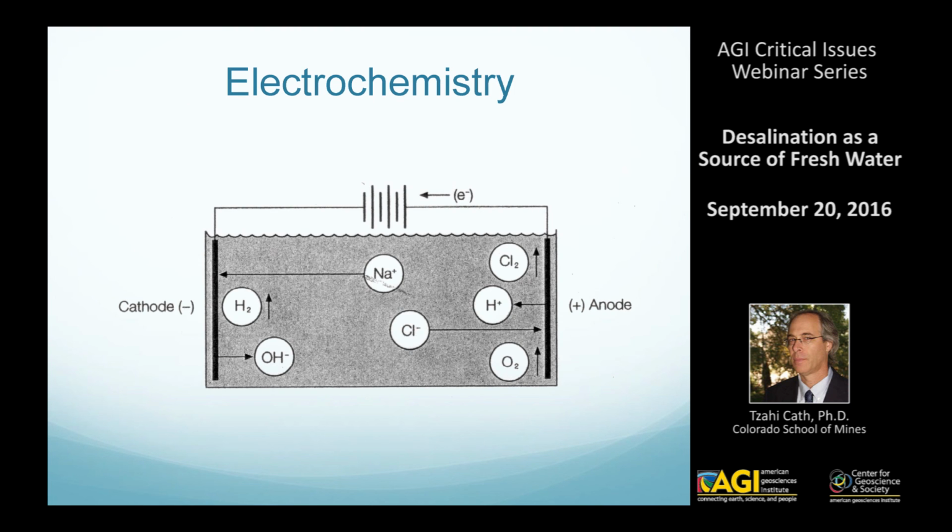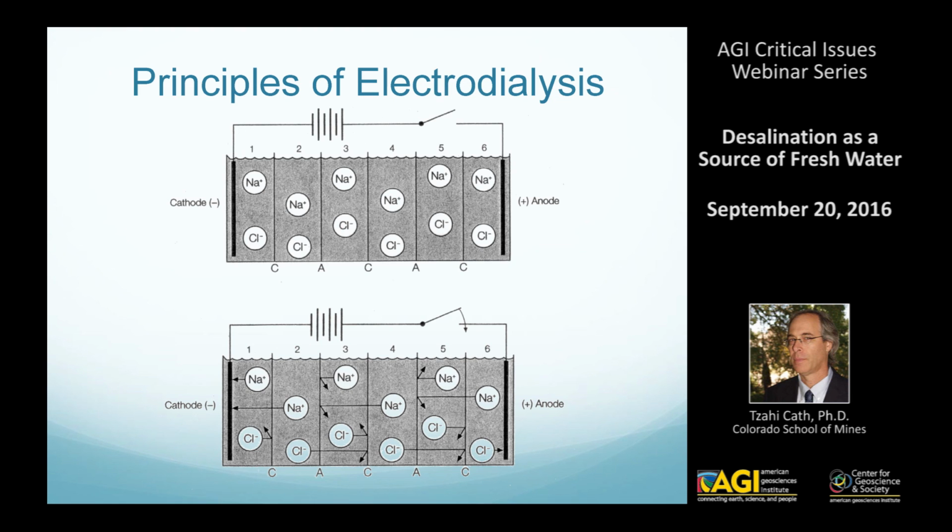Going to another unique membrane process that uses electrochemistry in order to do separation, in this case separating the ions, or removing the ions through the membrane and not the water. In this slide you see just the general phenomena where we produce an electric field between two electrodes in water. The cathode will attract the cations, and the anode the anions, and will be able to leave a void in the middle without salts. This is nice but inefficient, and for that people developed a process.